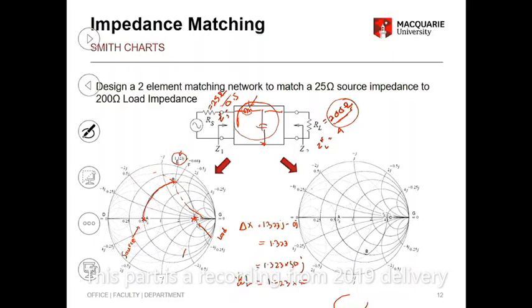But this circuit will work for any frequency. The reactance will stay the same depending on your omega, which is say 1 gigahertz. You can do 2 pi times 1 gigahertz. Then you can find L, and if you put that L in and then find the right C, this circuit will work for 1 gigahertz. So it's matched for 5 ohm to 200 ohm at 1 gigahertz. It won't be working for 500 megahertz because your L is different at 500 megahertz, right? Because it has a certain bandwidth. Right, so that's how you find the L.